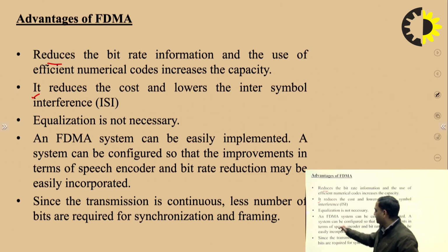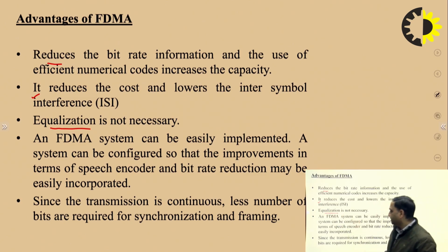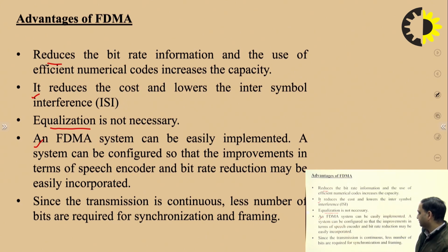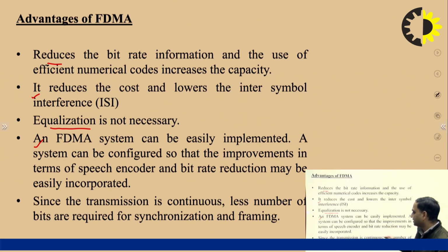In the case of the FDMA system, at the receiver side, there is no requirement for equalization, because the equalization concept is used to mitigate the ISI, right? Then next, the FDMA system can be easily implemented. It is not very complex to implement. The system can be configured so that improvements in terms of the speech encoder and bit rate reduction may be easily incorporated.